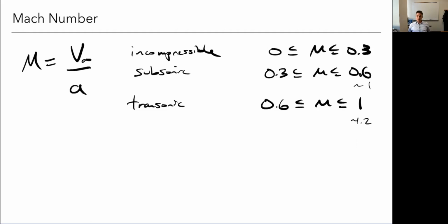So for example, a transport aircraft will say they fly at transonic speeds, and they're typically in the Mach 0.8-ish range, and this is where, again, the reason why we delineate, this is where there are no compressibility effects, or some mild ones. Here we're kind of at the edge, we're doing what we can to not have strong effects, but there could potentially be some strong effects of shock waves and things like that we'll talk about later.